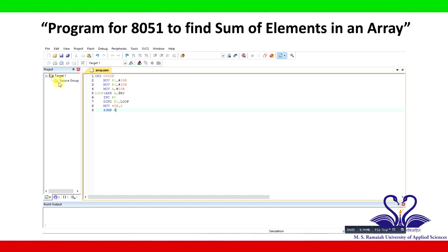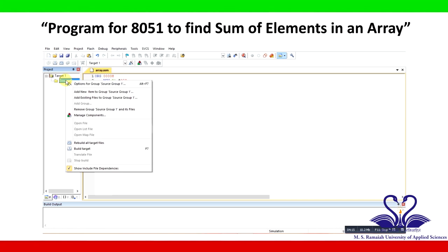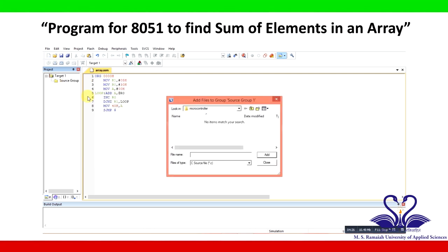Once these steps are over, we need to add this file to this project. How will we add it? Go to the source group icon and right click on that, so that we get the option, add existing files to group source 1. Click on this. Once this is given, this message will appear. What type of file have we chosen? It is an ASM type of file. So click on ASM source file.